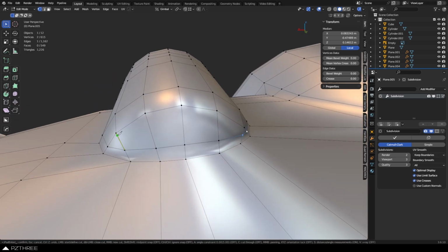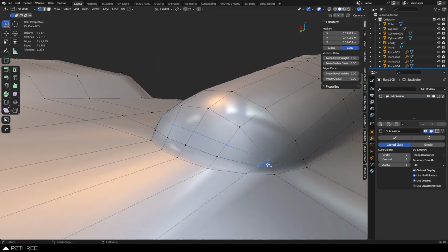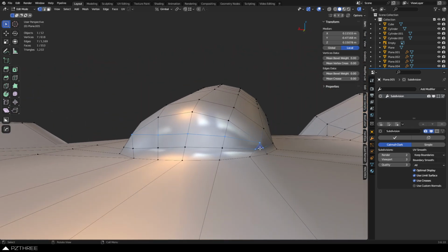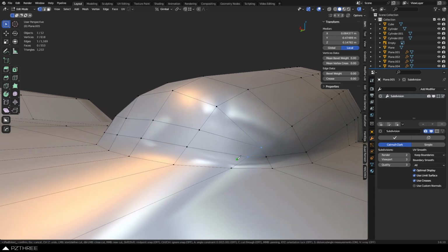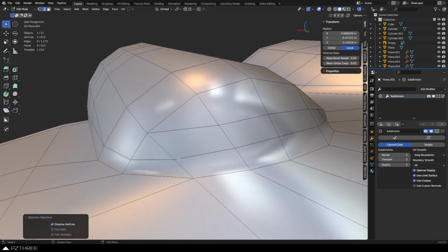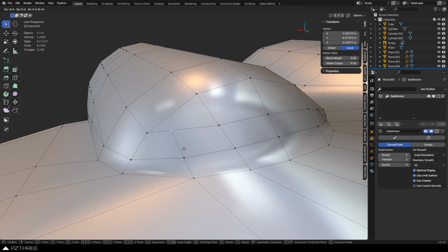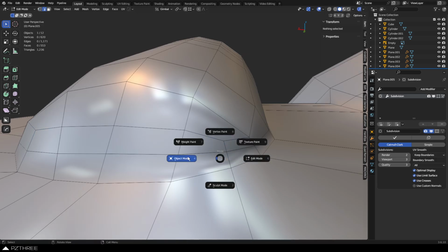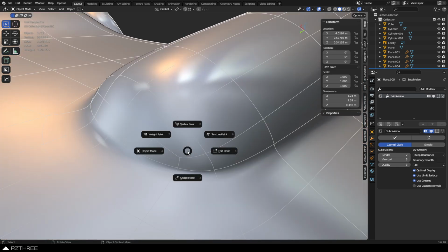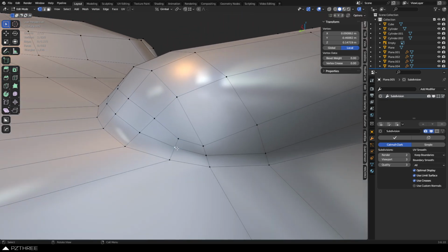We have another triangle over here, so we could probably run this out in this manner. Connected triangles. See if that works out for us for just a second. Not doing exactly what I thought it was going to do, but we're going to try that. Yeah, so sometimes there's weird connections. When you connect to the back of a triangle, it turns it into a quad. And so you can balance that out and wrap it up and make sure you keep that cylindrical shape perhaps, and boom. It should look a little bit better, but we created the pole manually. So we can just balance it if needed. Not a big deal.